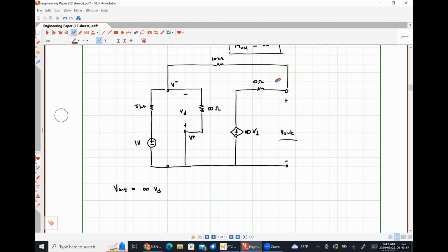Now, you might be saying to yourself, well, this doesn't really help anything because effectively I have two unknown quantities here. But I can rearrange this to find out effectively what's inferred, okay? So my differential voltage must be V out divided by infinity, just by doing the math there, which means my differential voltage by definition has to be 0.